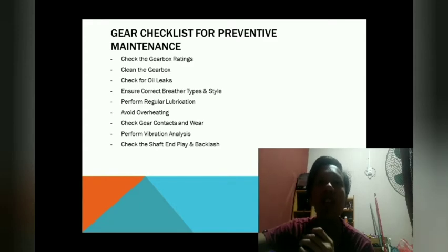Lastly, check the shaft end play and backlash. Is there any increase in the end play at the output or input shaft? Is there any increase in the backlash between the gear mesh? You can check this condition with the help of a dial indicator.